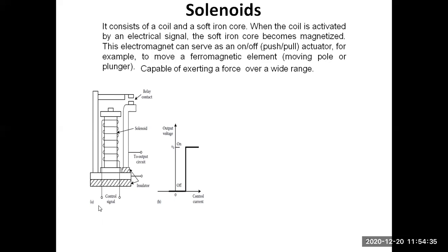So this is what is happening. This is a typical circuit. This is a relay actually. Let's say that this is the input circuit, and this is the output circuit. These are the terminals of the output circuit. This is a metal, and these two are insulators, and let us walk through the circuit. It will move from here all the way here, but here there is a disruption because there is a lack of contact between the relay contacts, right? Then again it is connected to one of the terminals. So in this case we can see that there is clearly a gap, so the circuit is incomplete. We cannot have any flow of current because there is a gap here.